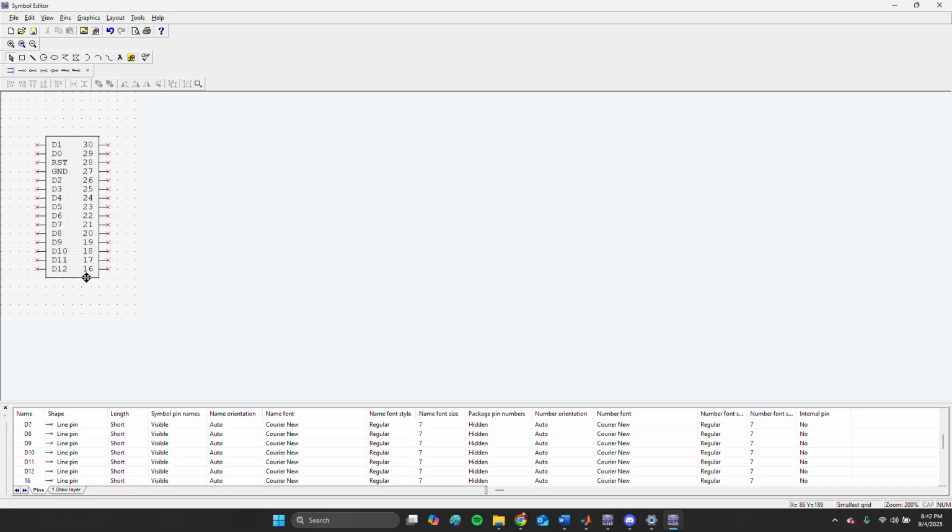And now it doesn't go from top to bottom for the next row. From 16 to 30, it goes from the bottom to the top. So that's something to keep in mind. And for 16, at the bottom right on this Nucleo board, this is actually the 13th digital pin, so you want a D13. And then from here, we have the 3v3 pin.